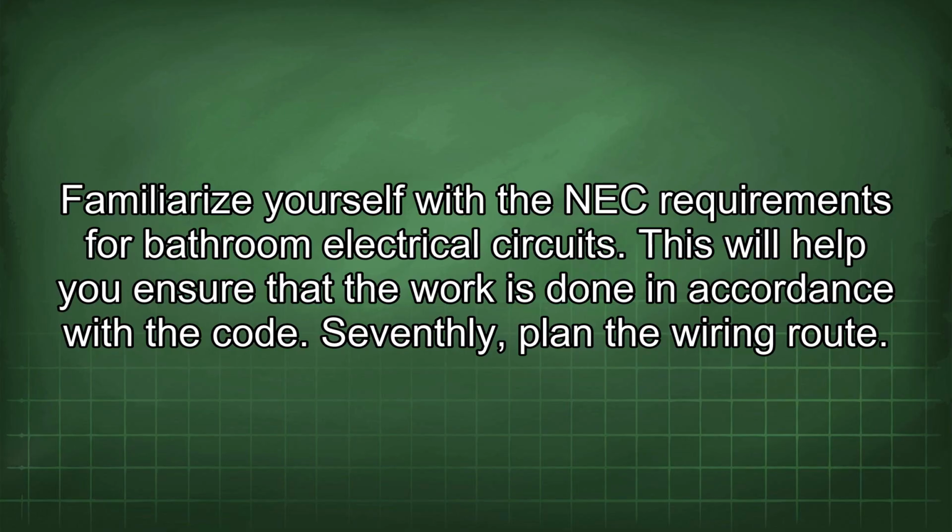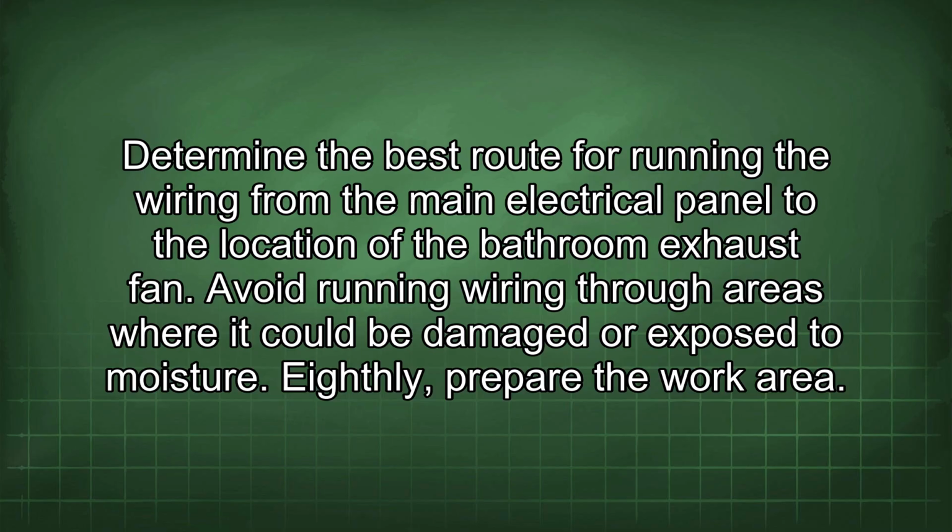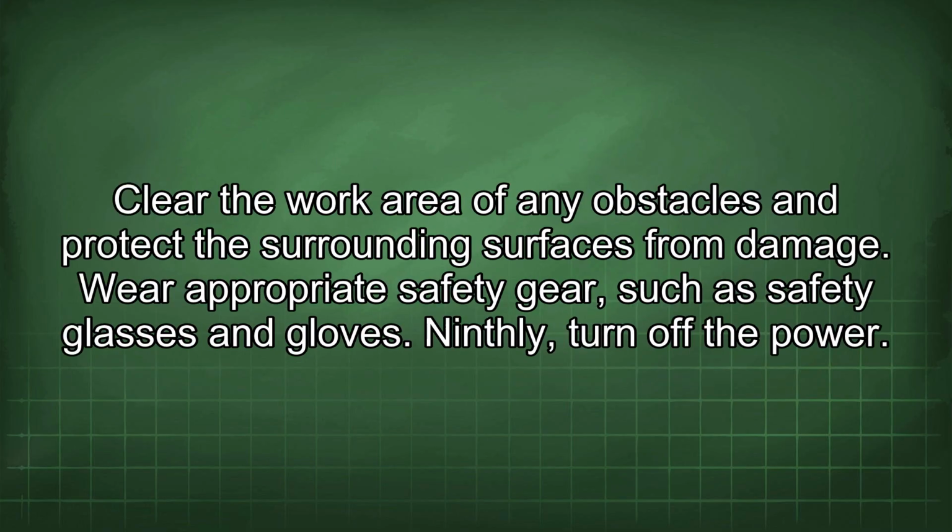Seventhly, plan the wiring route. Determine the best route for running the wiring from the main electrical panel to the location of the bathroom exhaust fan. Avoid running wiring through areas where it could be damaged or exposed to moisture. Eighthly, prepare the work area. Clear the work area of any obstacles and protect the surrounding surfaces from damage.